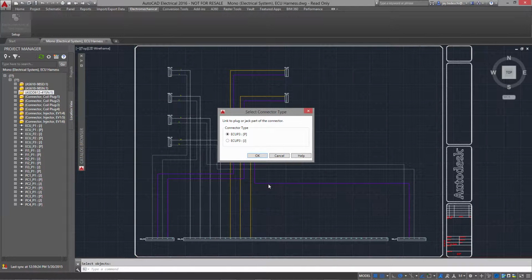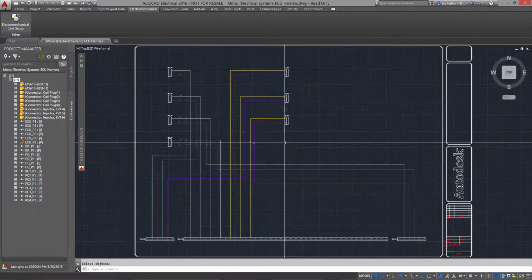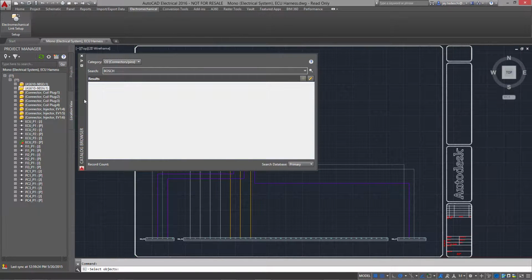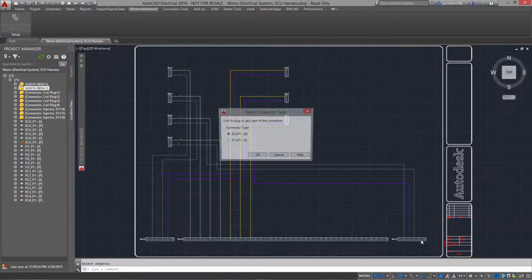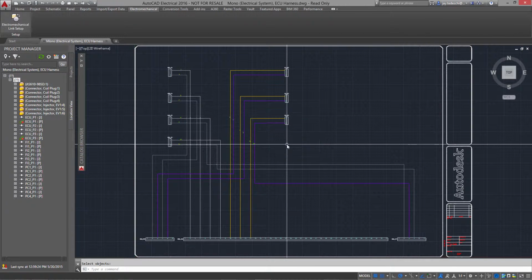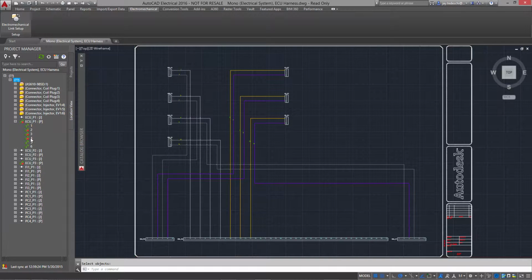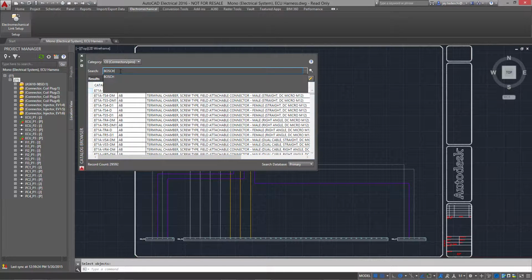So again, as you can see, the electrical browser itself is identical in both tools. What we're doing now is assigning the parts. As you can see in the browser there, the parts in Inventor can be assigned to existing elements in my schematic. So we'll go ahead and select this connector, for example. That's a plug, it's not a receptacle, so we'll select that from the option. And now it's showing us that based on the schematic, there are 3 wires hooked up to that connector at this point in time.